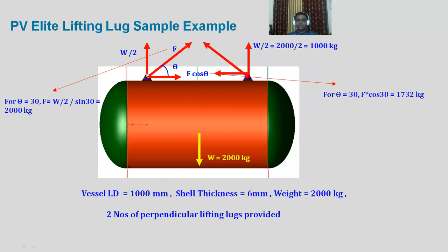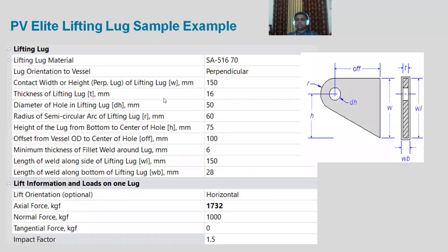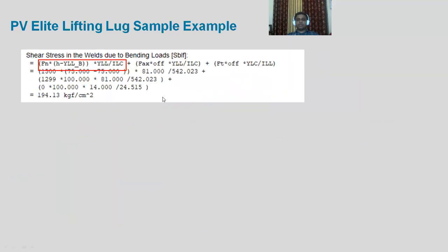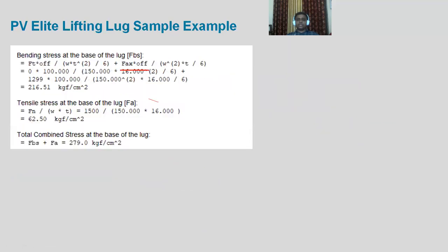So here we can see only because of this force there will be a tension coming. Because of this, bending will be coming. And because of the inner force or the tangential force, bending can be coming. But there won't be any tension because of these two forces. So tension can be created only by the normal force. And that's the reason why in that formula we can see the normal force was considered.